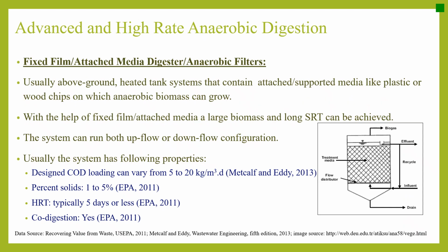Fixed film or attached media digester, or anaerobic filters. They are usually above ground heated tank systems that contain attached or supported media like plastic or wood chips on which anaerobic biomass can grow. With the help of fixed film attached media, a large biomass and long SRT can be achieved in the system. The system can run in both upflow or downflow configuration.